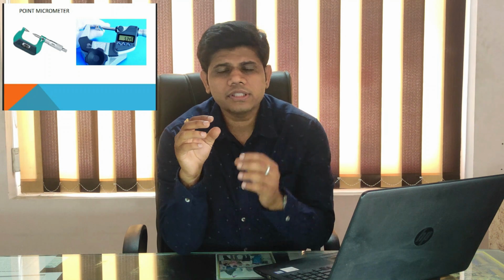Generally, in some cases, as you can see on the screen, there is a job with a very narrow surface, and you have to go inside that portion and measure the diameter or the length. In that case, you have to use a point edge micrometer, which will be helpful in measuring that portion exactly, with accuracy also. So according to the requirement, you can choose 45 degree or 30 degree and get the exact result.